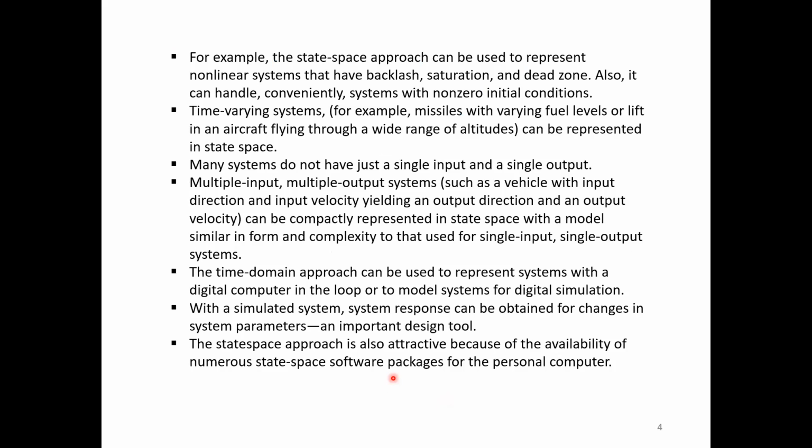The state space approach can represent nonlinear systems that have backlash, saturation, and dead zone. Also, it can conveniently handle systems with non-zero initial conditions and time varying systems. That means missiles with varying fuel levels or lift in an aircraft flying through a wide range of altitude can be represented in state space. Many systems do not have just a single input and a single output.